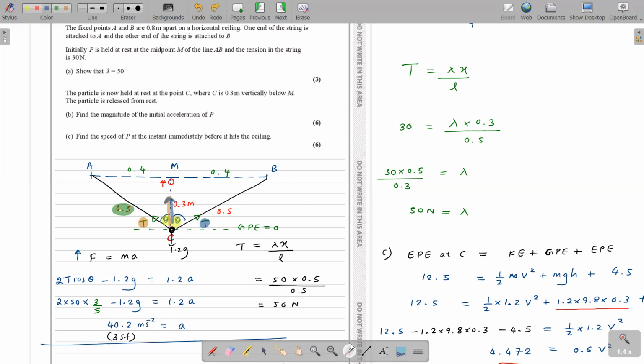Okay, so in these kinds of situations, if they ask you to find the speed, you can't work with this acceleration to any point other than the initial point. There's no point working with this acceleration, and you cannot treat it as constant. That's very important. So in a situation like this with changing acceleration, the only way you can find a speed is by considering the work-energy principle.